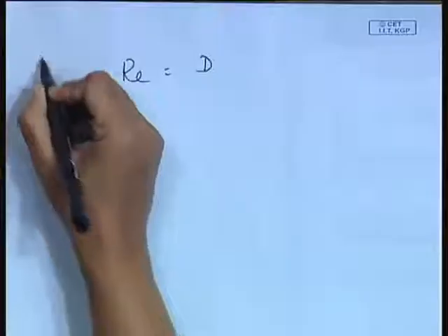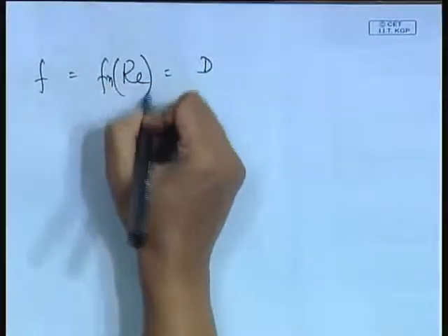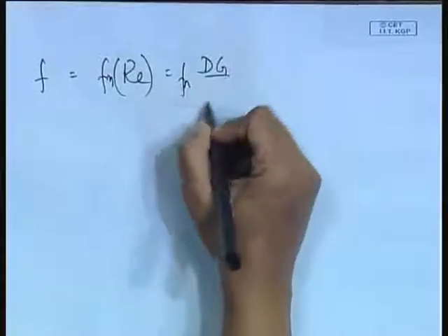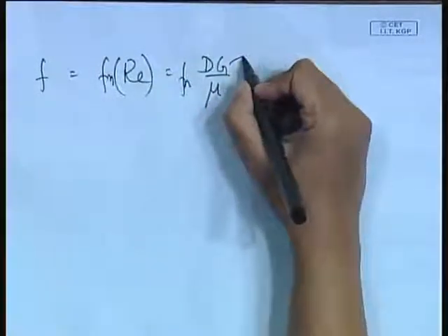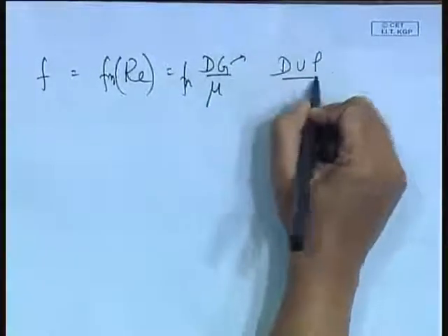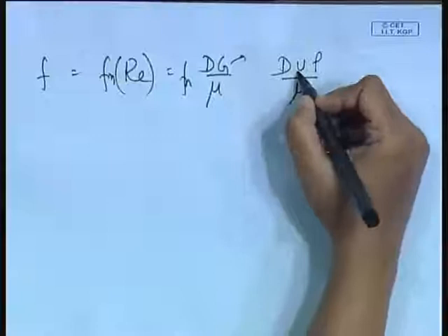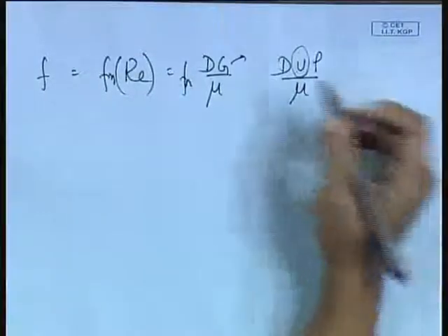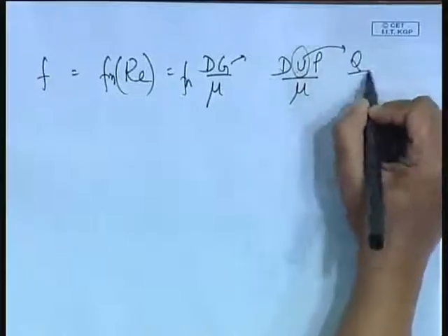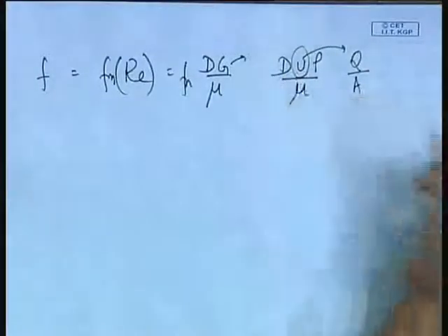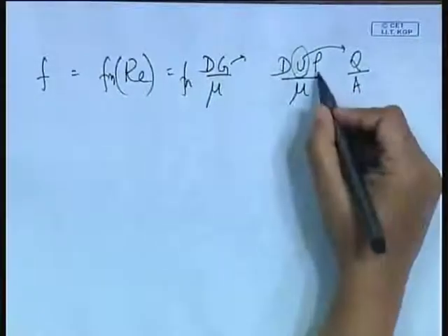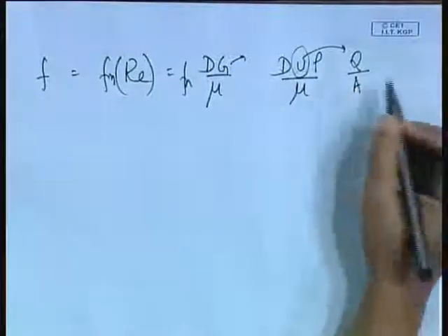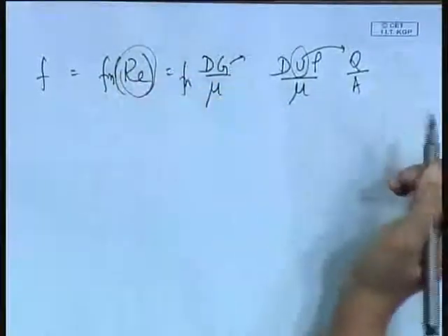Okay. So the friction factor for single phase flow is a function of Re, where Re equals dG by mu. This G is better written as d u rho by mu. There was no chance of u varying within the flow, there was nothing like in situ and input velocities. This u was simply, you measure the volumetric flow rate, divide by the cross sectional area, you get u. D is the pipe diameter, rho and mu are simply fluid properties. So this Reynolds number was an input there.